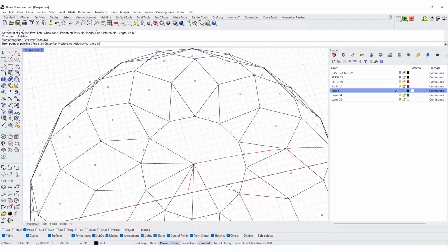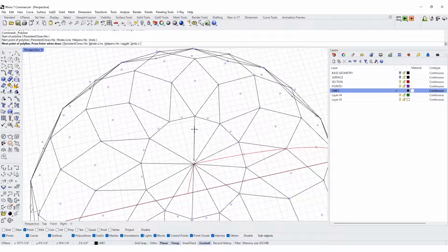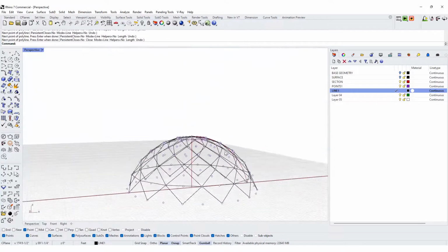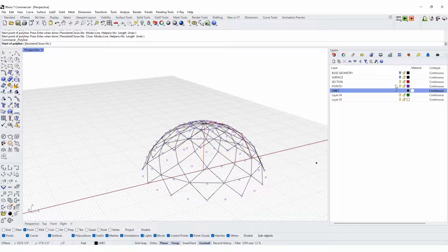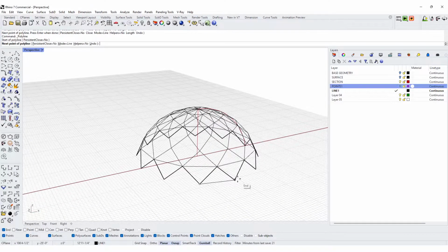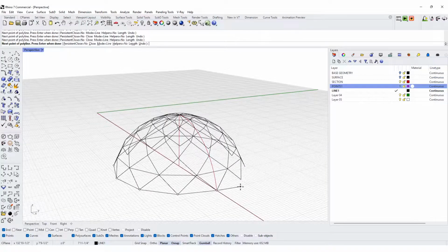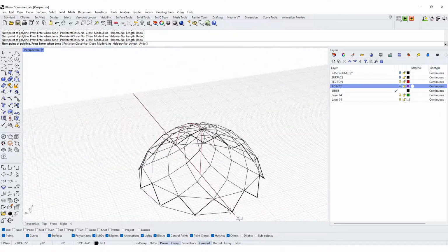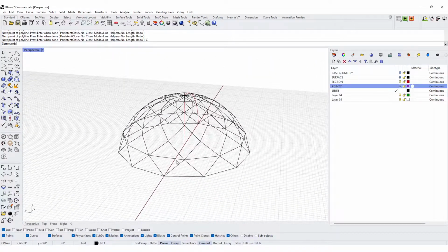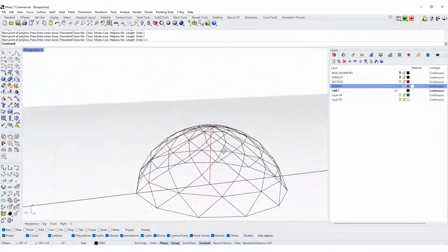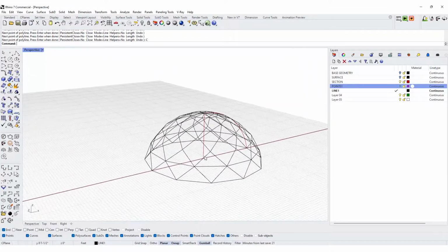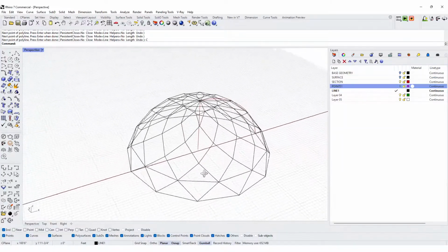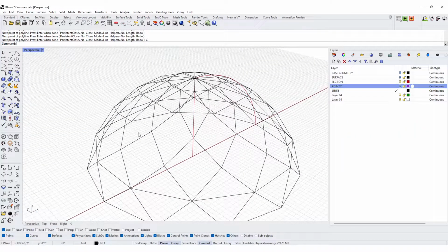The other trick is going to be start here, midpoint, and then here, and then we'll skip one. What we don't want is redundant lines. So now with this, we can hide our points. Now we can go to endpoints and work our way around here. C, enter to close. Cool. So that goes over the technique for creating those segments.